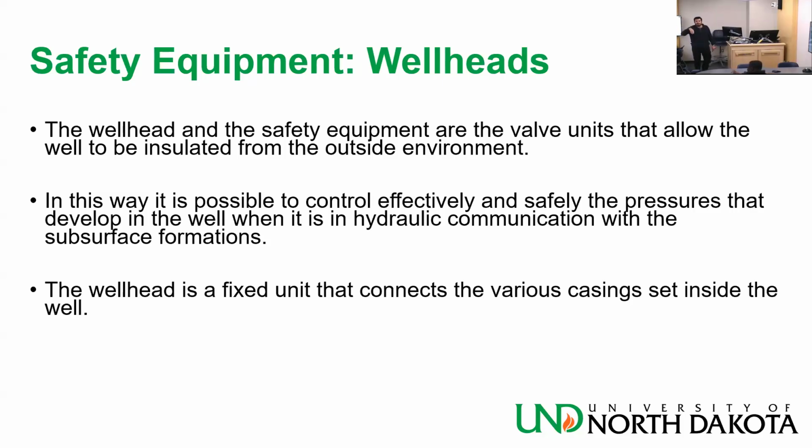It's just that during drilling, we call it BOPs. During cementing, there is a cementing head on top of the BOP, but that's considered basically to be on top of the wellhead. When you fracture, there is a frac tree. And when you produce, it's a Christmas tree. They are all installed on the wellhead. That's what you see on the surface.